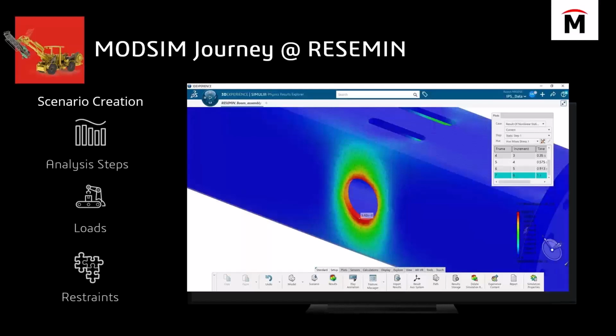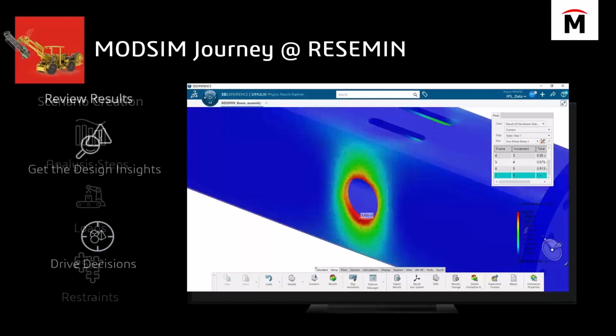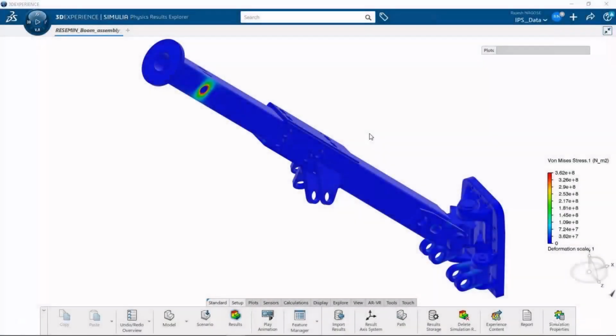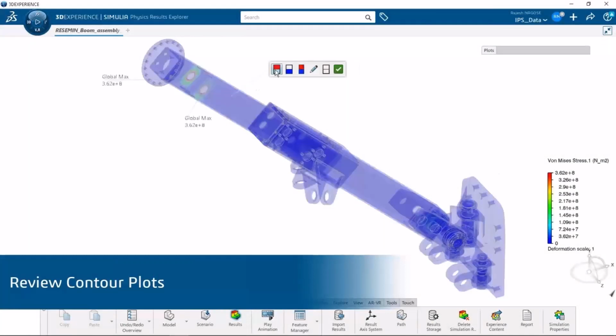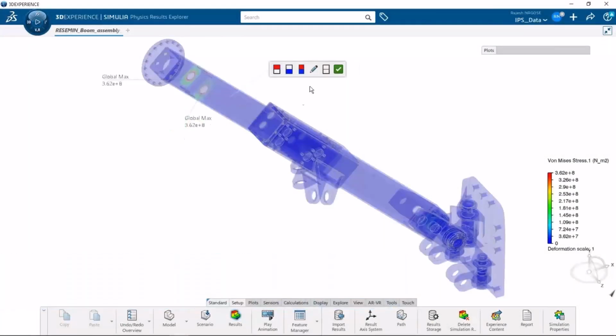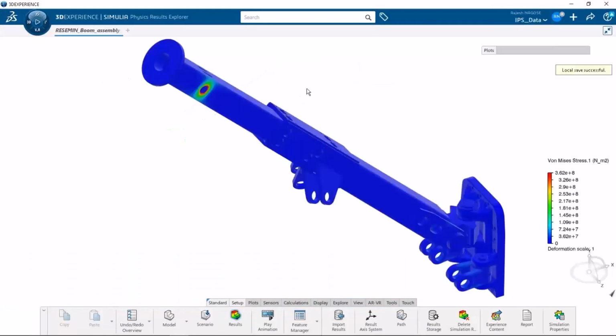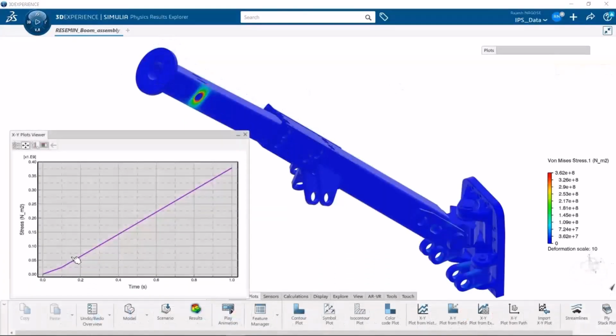Okay, so I define my boundary conditions and setups for the analysis case in the scenario, enough to produce multiple load cases there and produce some fatigue results. There are some built-in results that are going to come out, just like in SOLIDWORKS when I saw stress, displacement, factor of safety, and then I can ask for more results or go around and probe and see what we've learned. So the main KPIs that I want to review here is going to be von Mises stress, max stress in here. So let's probe and set up a flag for what the max is.